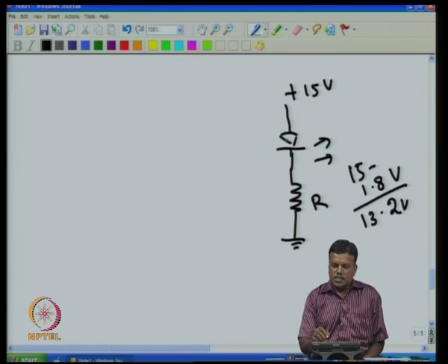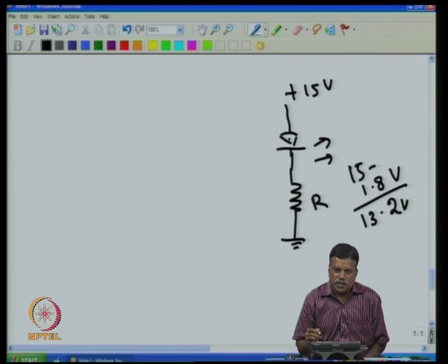But we know that this LED needs about 10 milliampere current to glow bright enough, and we should not pass too much current because then the LED also goes bad. So, I take 10 milliampere as the acceptable current, which I have to get from the data sheet.